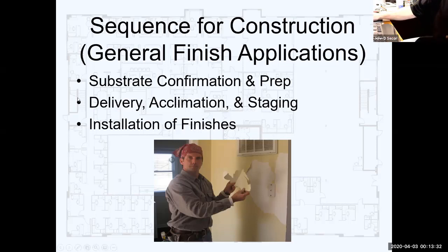So, moving on through this stuff, hopefully you've made the correct specification for the substrate, so all that's been confirmed and applied properly. The other aspect of this is that some materials, like wood, require acclimation. That means that they must be delivered to the job site between 24 and 72 hours before installation.